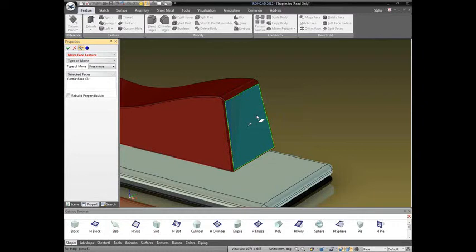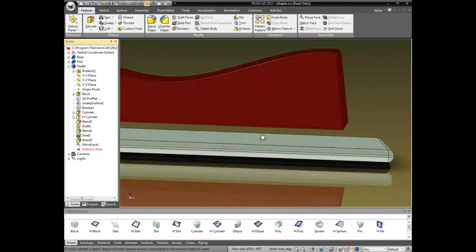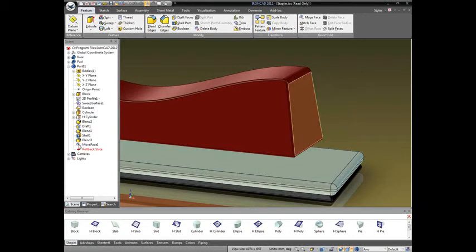So I select the face, turn on the triball. Maybe I'll pull this out a little bit, and you can see the motion here. Maybe I'll rotate this up a little. Maybe rotate about both axes just to give it a bit of a twist here. Maybe we'll twist it this way. There we go. Hit OK, and you can see it made the rotation of the face, but it created a